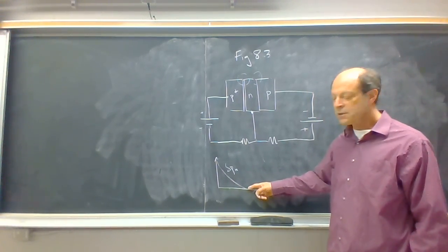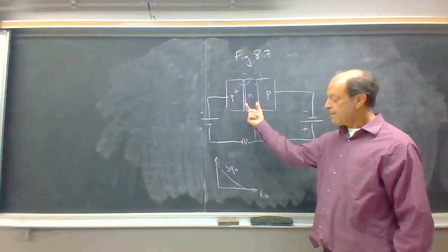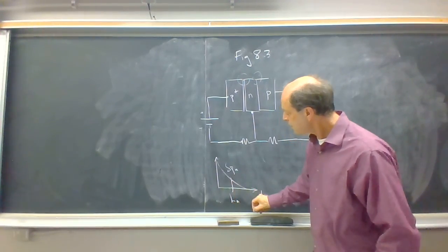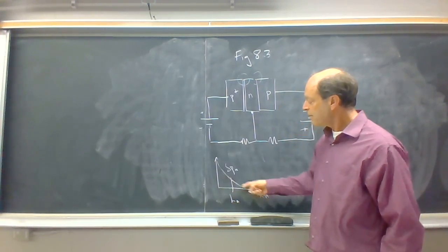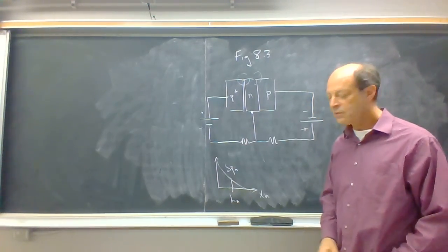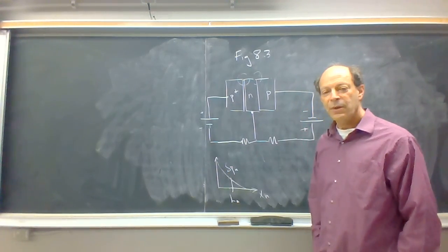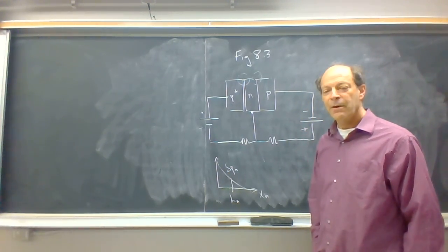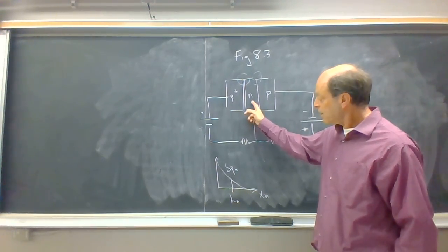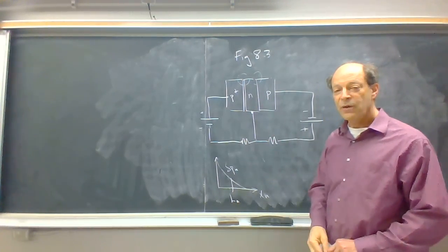Remember that the diffusion length is a measure of the decay distance of that minority carrier concentration. As long as we can keep our second junction well within one diffusion length of the carriers in this N region, we can have access to those carriers across this reverse bias junction.